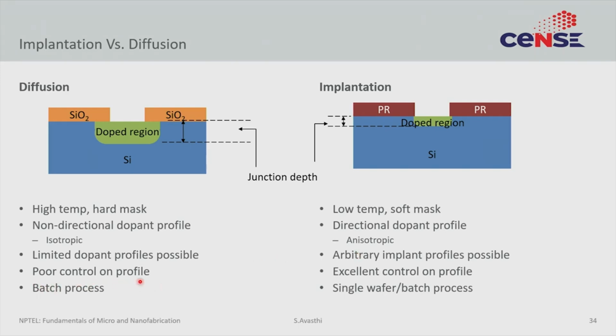If you remember, we discussed a two-step process. And the reason we needed a two-step process was it was very hard to exactly control the diffusion profile, get exactly the same peak concentration, get exactly the same depth, all because it's a process that is very hard to exactly control. Ion implantation, on the other hand, is much more accurate. The dosage can be measured with arbitrary precision because it's equivalent to measuring charge or measuring current, and we are very good at that.